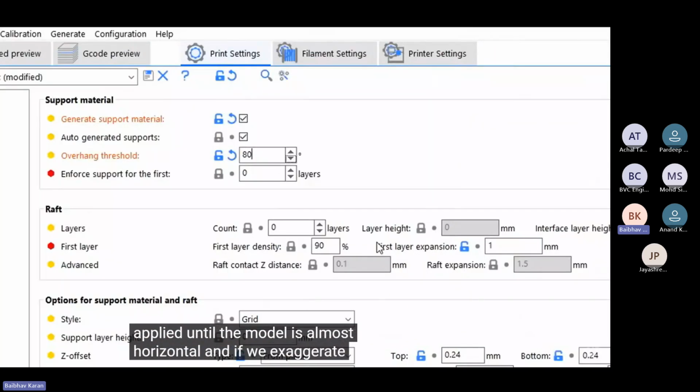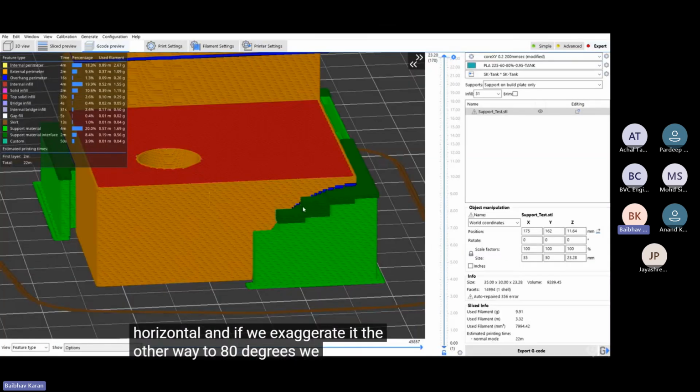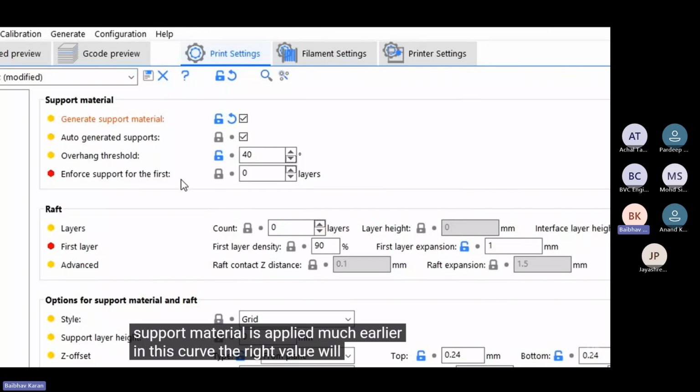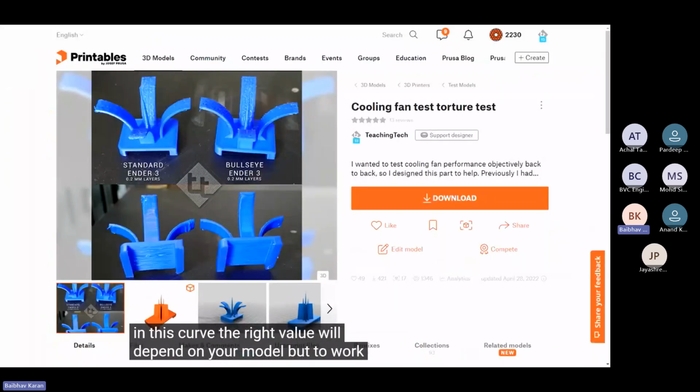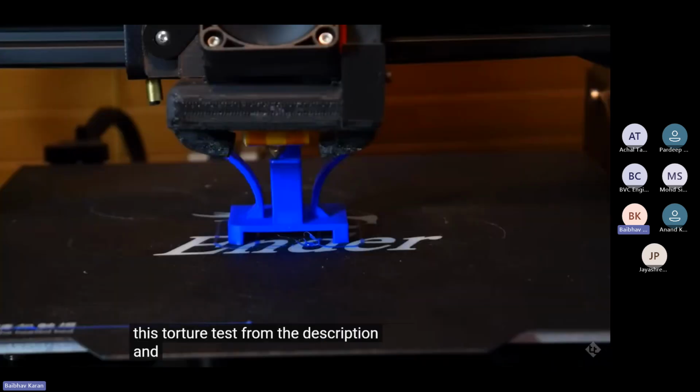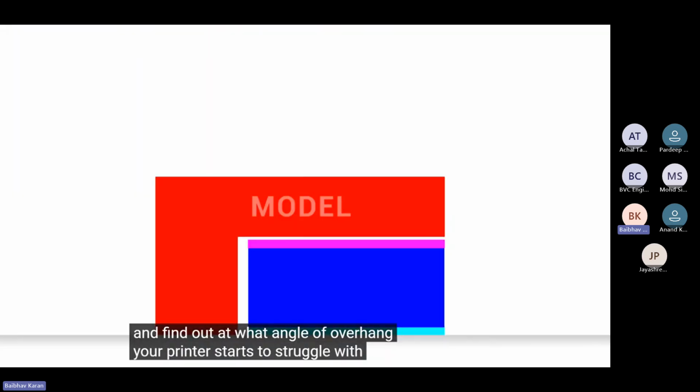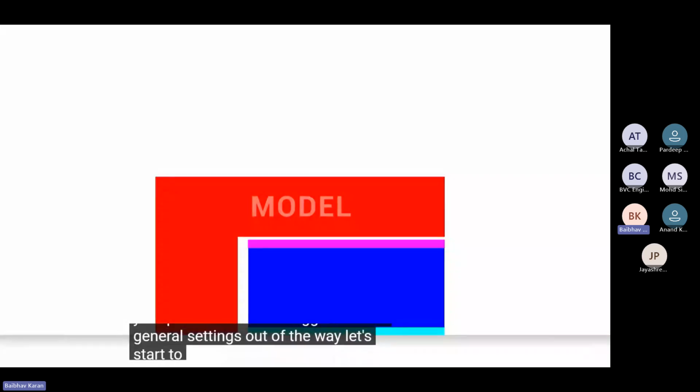And if we exaggerate it the other way to 80 degrees, we can see that support material is applied much earlier in this curve. The right value will depend on your model, but to work out a good default, you can download and print this torture test from the description and find out at what angle of overhang your printer starts to struggle. With the general settings out of the way, let's start to look at specifics, starting with our bottom or raft section of the support.